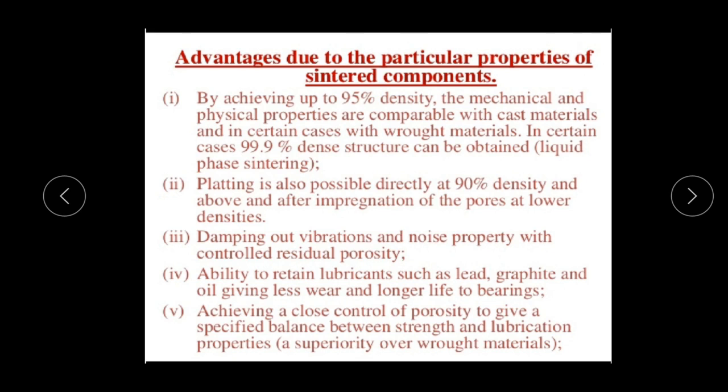The second one, plating is also possible directly at 90% density and above, and after impregnation of pores at low density. The third one is damping out of vibrations and noise with a controlled residual porosity.